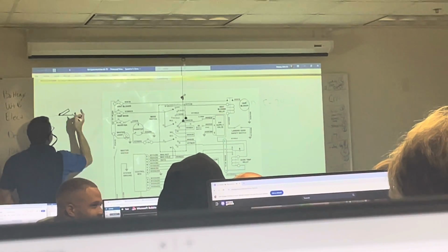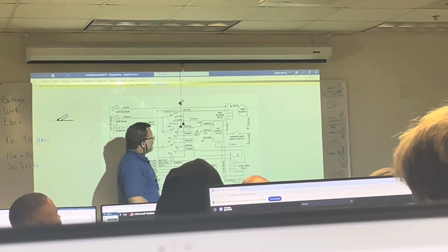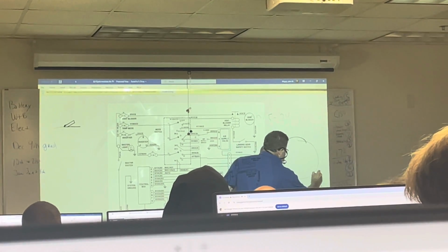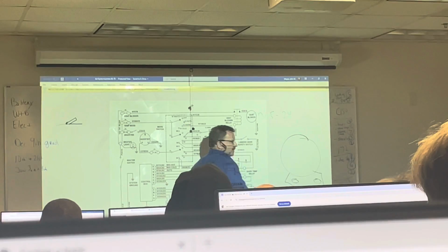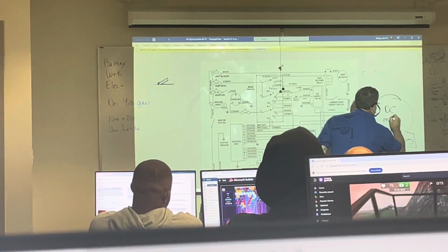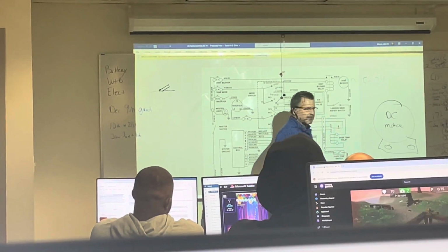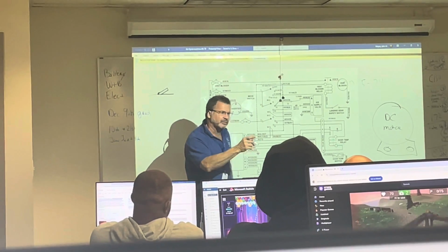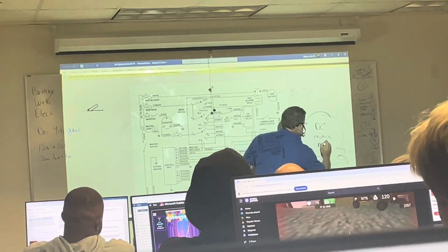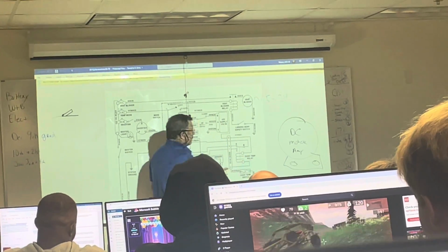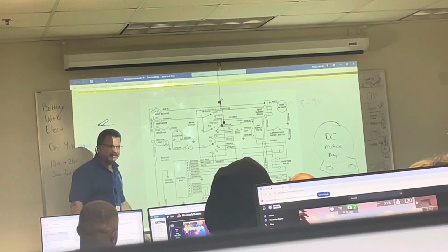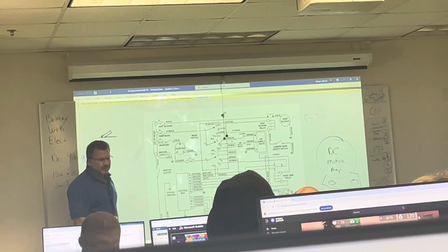So in the cockpit, I have this very small switch. All right? And very small. But the vent blower is this big in circumference. It's big and it's mounted on the fuselage, big bolts and all that. It's a pretty big unit, right? Yeah. And it's a DC motor, because we know we're working with DC. Right. And what do we know about DC motors? They draw several times the rated current, right? Right. So they are going to be a high amperage for our power, right? Now, to turn that motor with that switch, is it possible? Yeah. That switch wouldn't last very long, no how.